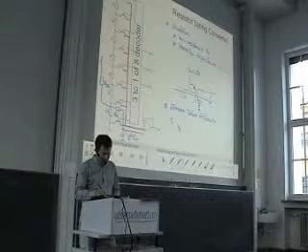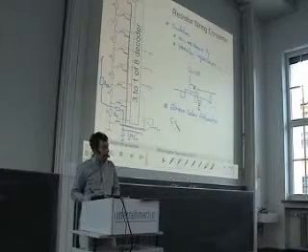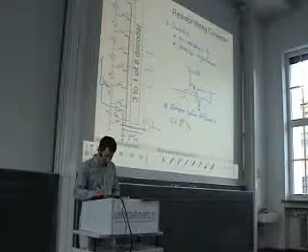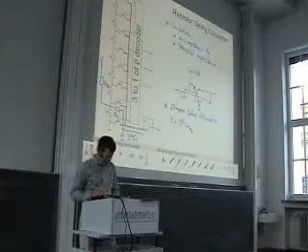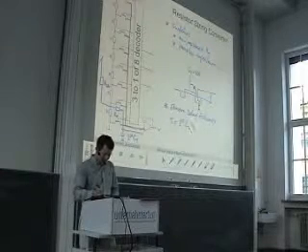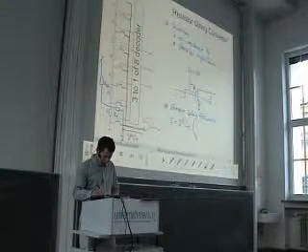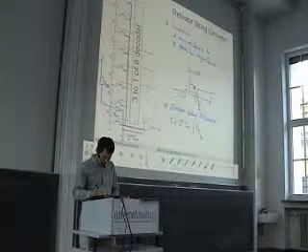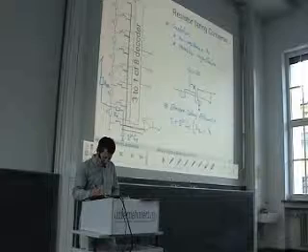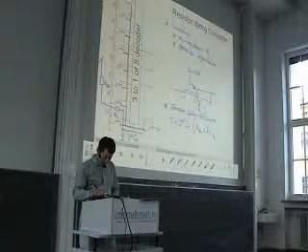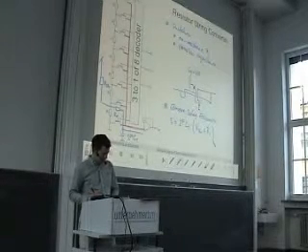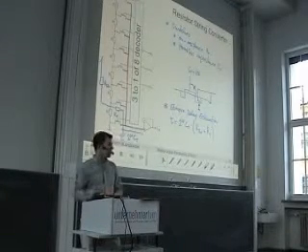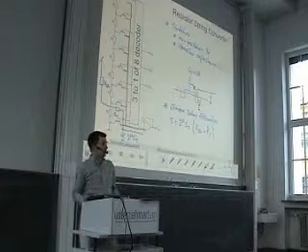So the delay estimation is the cap that we have at this node, which is 2 to the power of n times CT, multiplied by the path resistance, which is R string plus R transistor. So I neglected all the caps in this string because they are already charged.